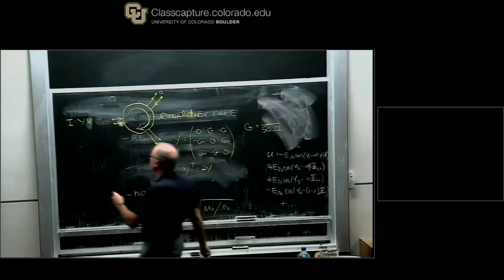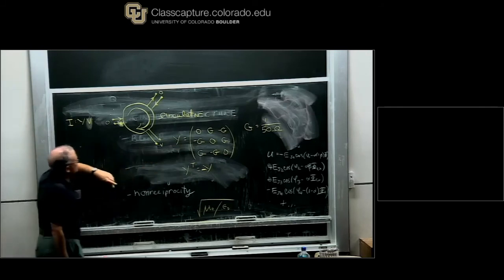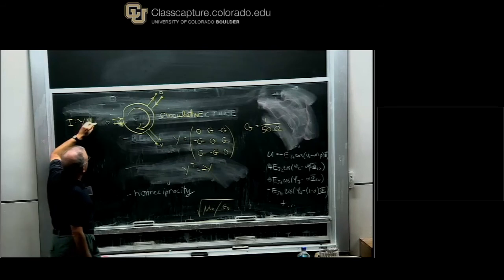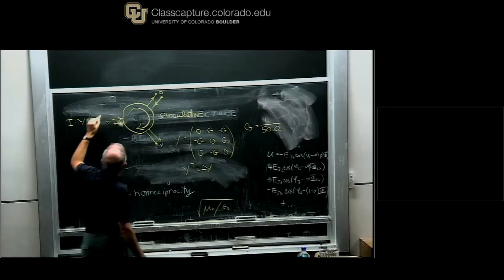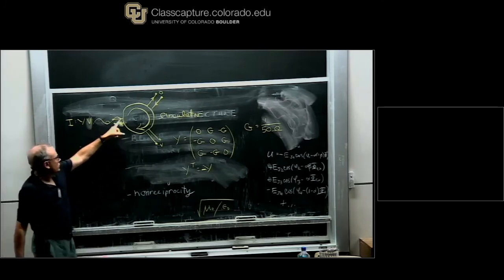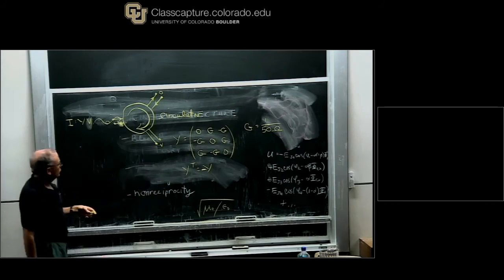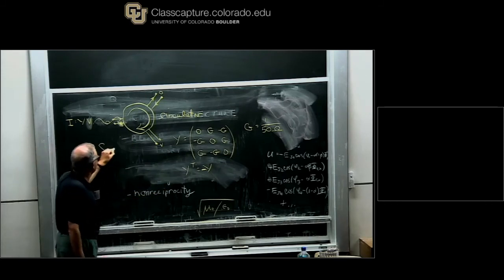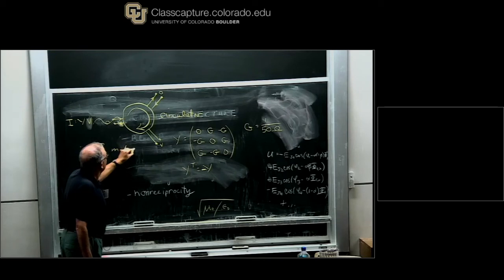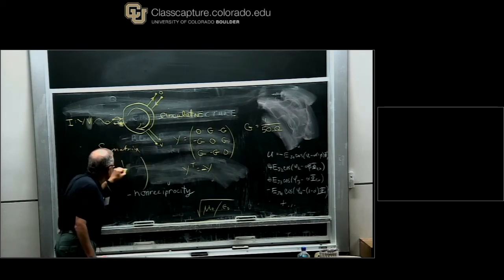The thing that's actually of interest about this is more of its wave signal. This is sort of a DC description of what it does. But a more informative thing is to say what it does if a wave impinges on it. And wave means that it's a wave of voltage with an accompanying wave of current. So you need to know the S matrix. And the corresponding S matrix for this just has this simple form.